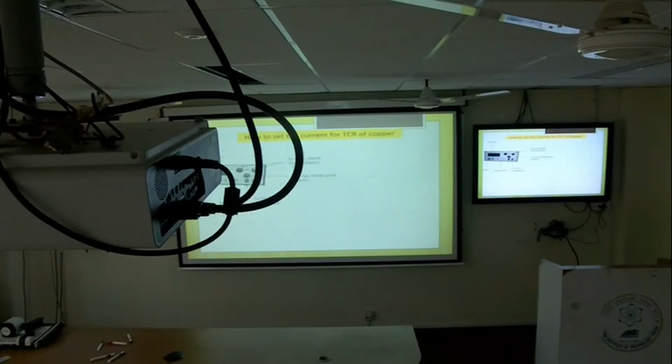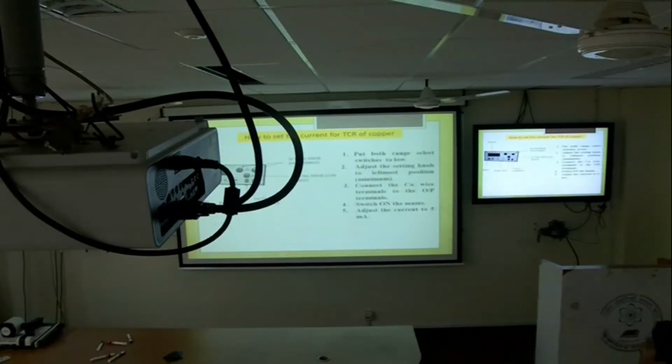Okay. So how to set the current for the insert? First of all, we have the display on this side. This is a range switch, low and high. When it is low, a small resistance comes into the picture, that drops the current. When you put it high, the switch is bypassing that resistance, providing the shortest path to the current, so the current starts increasing.